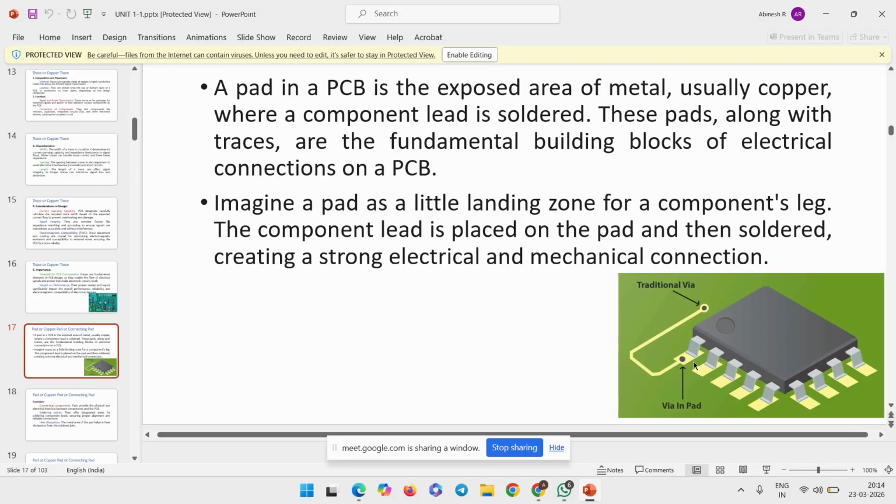Consider a pin that is 1 mm in length. If you provide 0.7 mm, the pad becomes shorter, so the pins are placed partly outside or cannot be placed properly. So we must provide proper input for pad creation, which means length, width, and the spacing between the two pads. What is the name of that spacing?